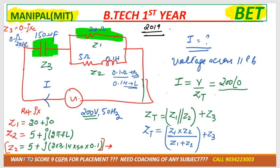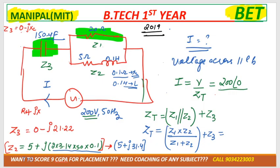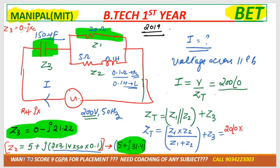2 given, pi given, F given, and C is given, 150 microfarad. 150 microfarad means 150 into 10 raised to power minus 6. Clear? Note it down up to here. See, after solving, you will get Z2 as 5 plus J31.4 and Z3 as 0 minus J21.22. Now we need to substitute the values. Z1 is 20, right? Angle 0, multiplication.